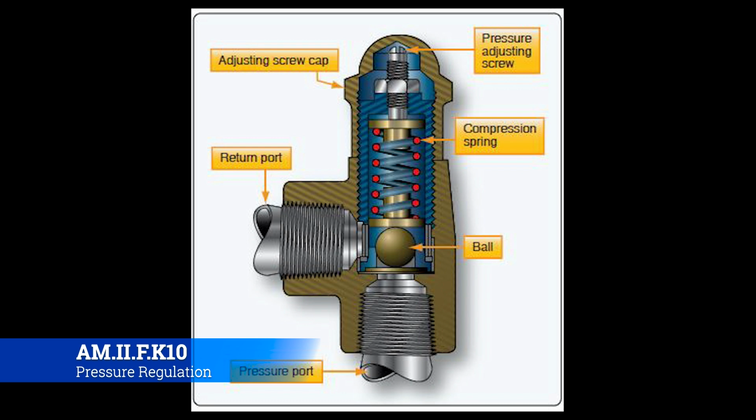Now, this pressure relief valve works like a regulator, pretty simply, where pressure comes into the valve. It has to then go around a ball that is pushed down on by a compression spring, which is then pushed down by an adjusting screw. Now, the state of that ball basically works like a faucet in your bathtub. It constricts the flow of the hydraulic pressure, which allows for it to be a little dribble or a gushing flow, depending on how it's set.